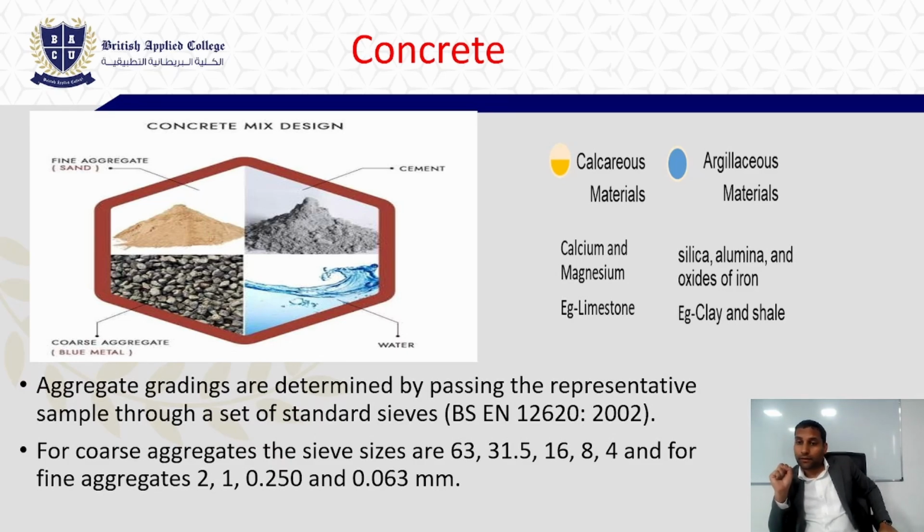But that is wet concrete. To calculate dry concrete, you need to multiply it by 1.54. That's how you will calculate dry concrete. Now you need to also understand that dry volume is more than wet volume, because once you add water, the sand and cement will come close together, the voids inside will get filled with water, and the volume will reduce. So this is the basic idea. That's why we multiply it by 1.54. A 54% increase is there in general. So we multiply it by 1.54 and we find out the dry volume.